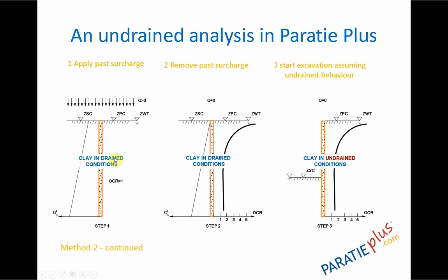So just having drained conditions, the effective part of the stress will store the effect of past surcharge. Then we must model a second stage as well, considering drained conditions, in which we remove that over-consolidating load, and we will have an over-consolidation profile like this.